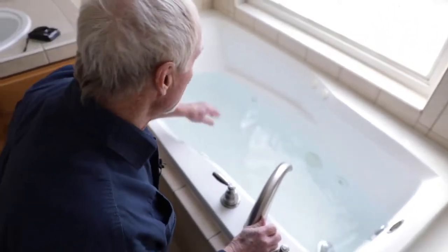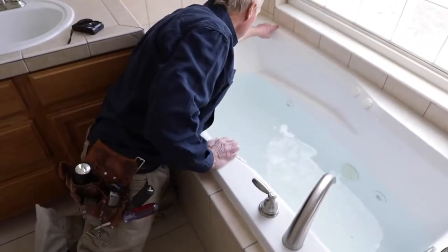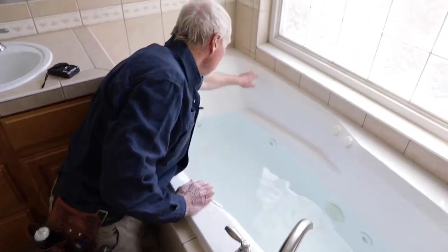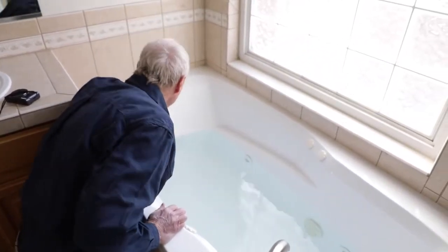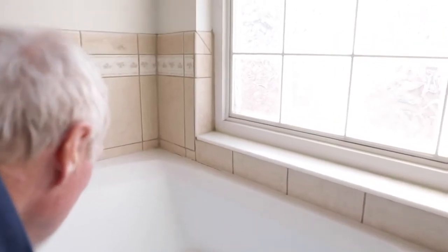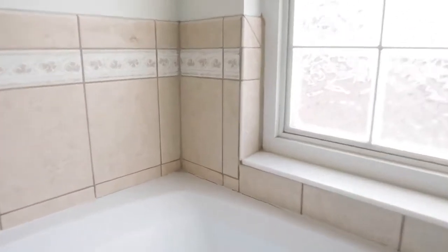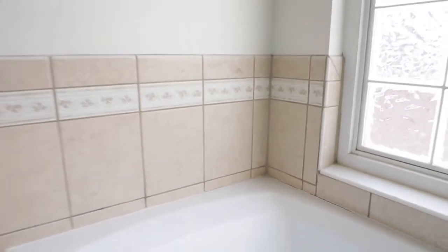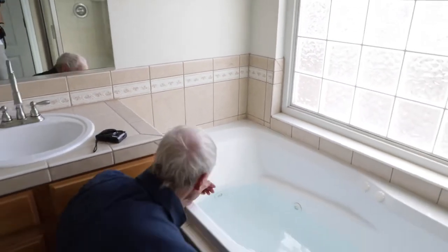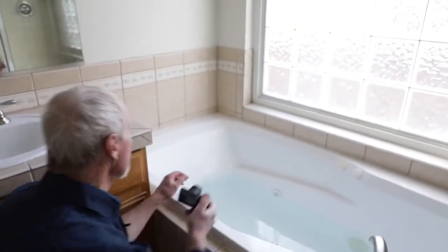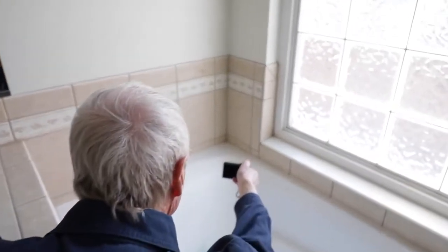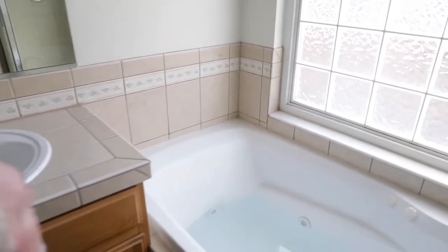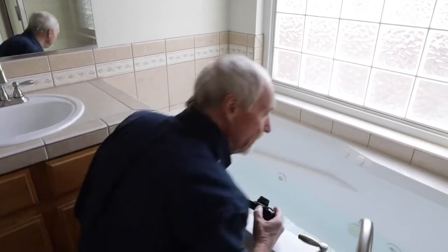So one thing I see as I'm looking at the tub is I can see here that our caulk line has broken loose. Could be that over time the weight of the tub has pulled it, or keep in mind that the material that the tub is made out of is different than the tile, and you have differences in thermal expansion and contraction between the two different materials. But I don't think that's any big indication of a problem. I just think we need a caulking repair done there. And I will, of course, take my photo showing the caulking repair is needed there.